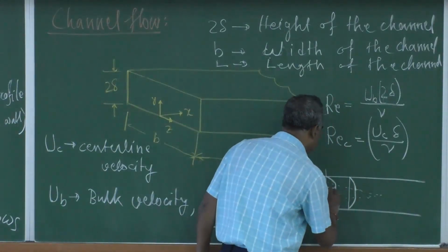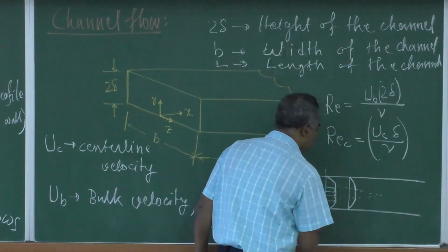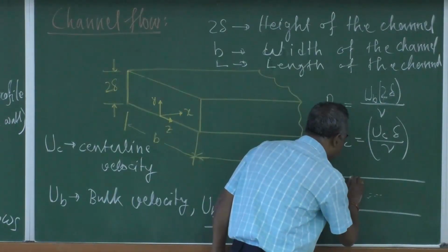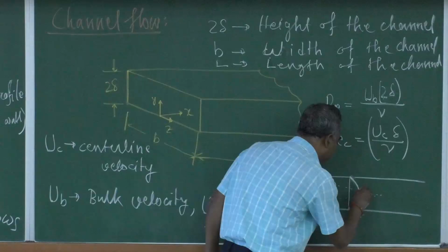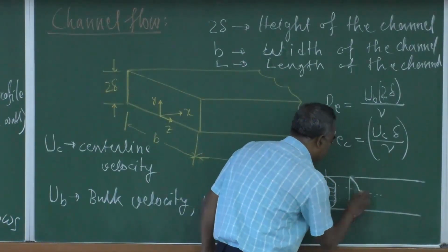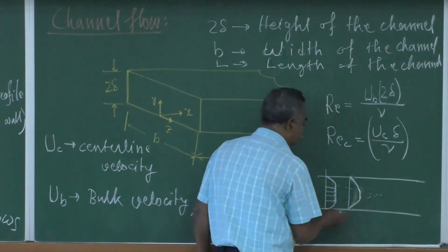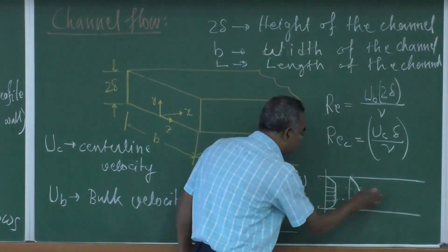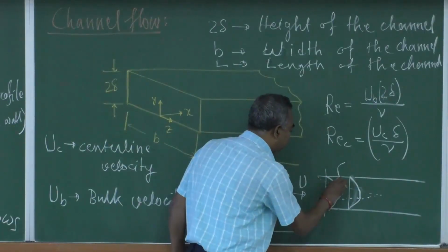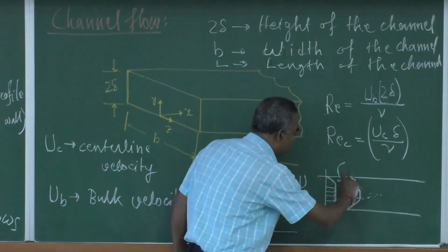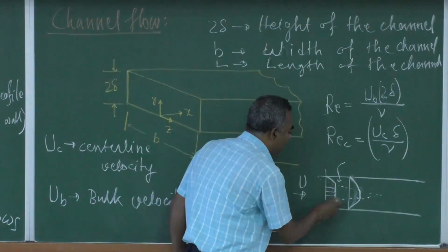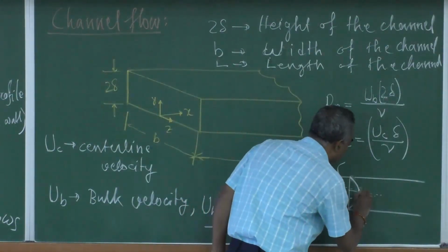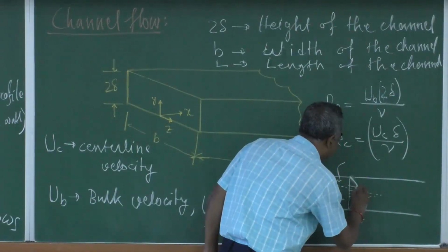Here, if you see, it is a constant velocity. There is a slight proportion issue in the drawing, but as it goes downstream, the velocity should be at the center line velocity within this potential core. This is known as the potential core or potential regime. This is the viscous regime, within the boundary layer, and outside of the boundary layer the flow can be considered potential flow. So the velocity should increase, and the profile should look something like this.